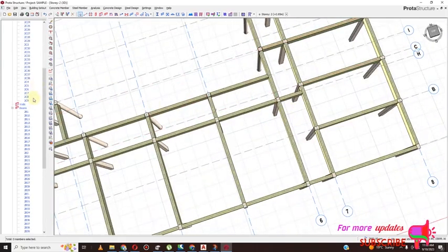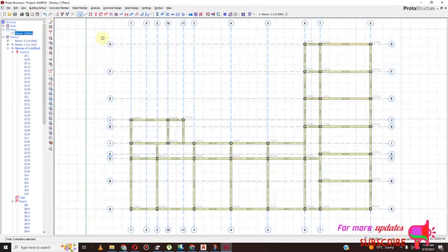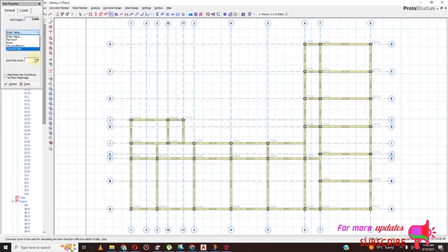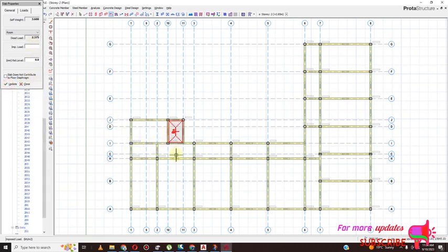So I'll go to plan view. I will insert my slabs. So I need a 150 slab, cover 25, and then loads, self-weight, that is automatic. I need dead load for room. Then imposed load for a school should be 4. Then update and then start inserting my slab.